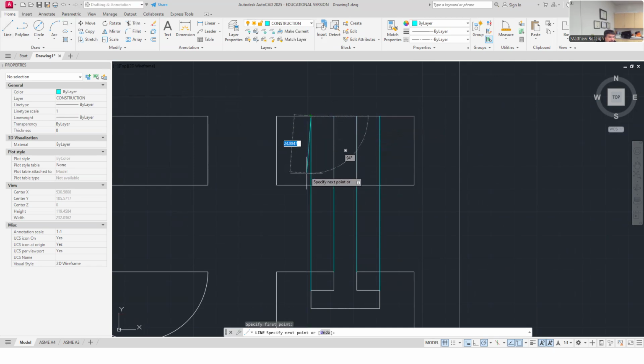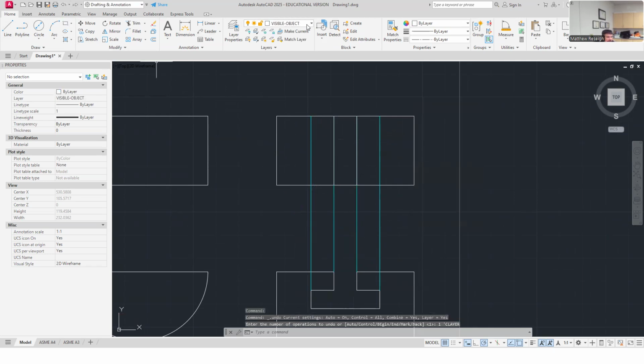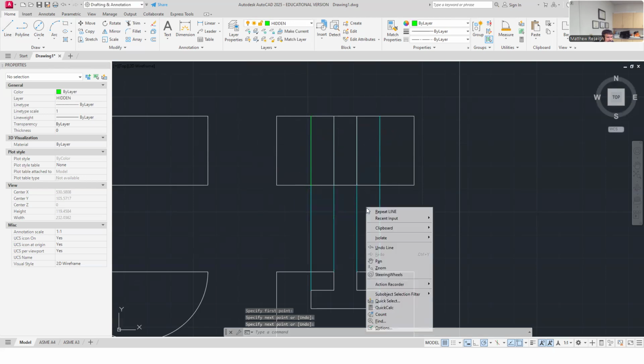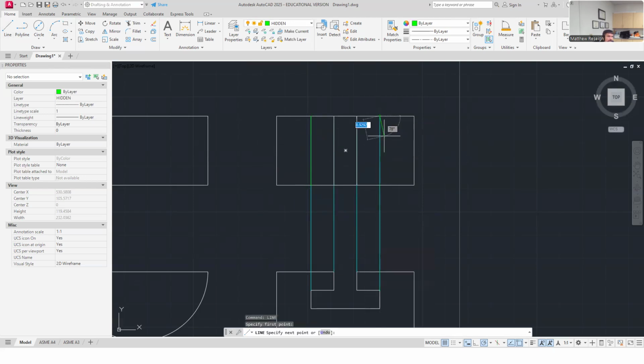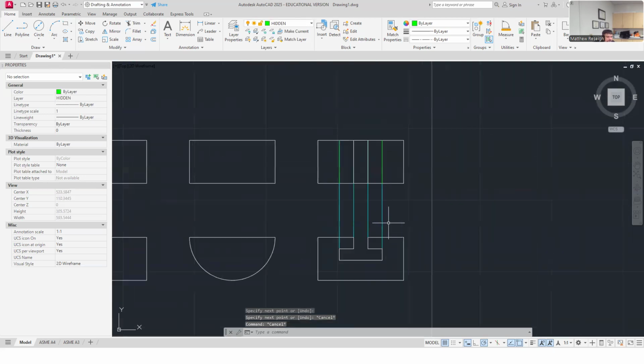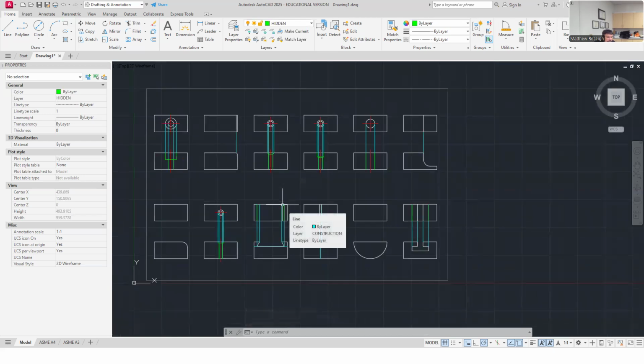And then this one will be hidden. I did it as construction because I was wrong. So let me undo that and do my hidden line work here. Hidden is what I really want. I'm going to trace this over with hidden. And I think these are done. If you label them, extra points for you. If you don't, it's okay. There's no center lines on those.